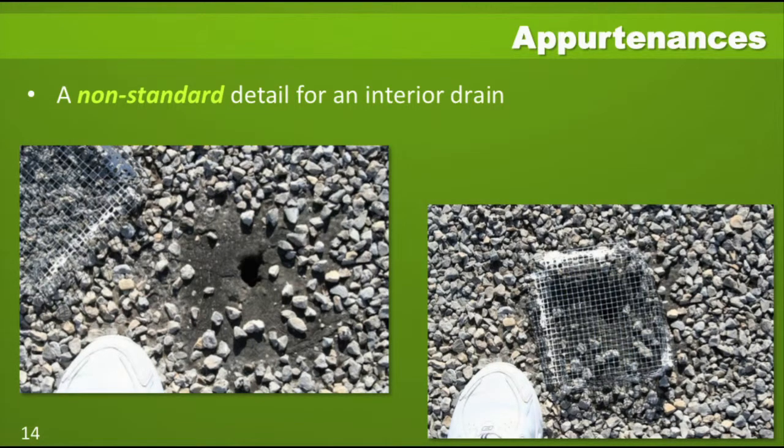These photographs show the lack of a proper strainer. There is a metal screen that's there that is somewhat attached. This is intended to be a drain, even though it's a very small opening and there's really no detailing at all to it.